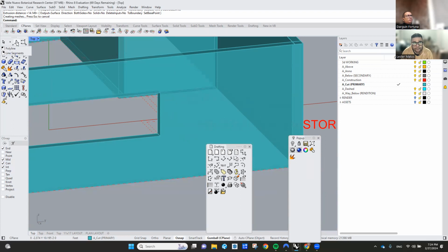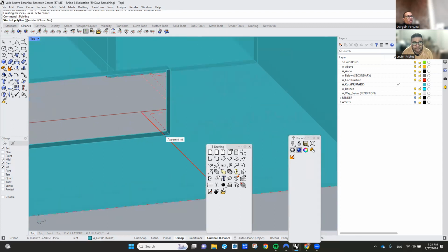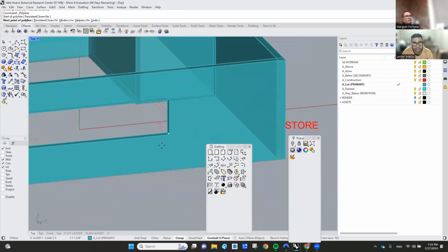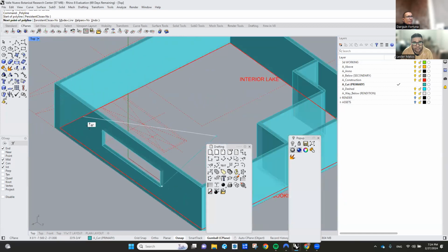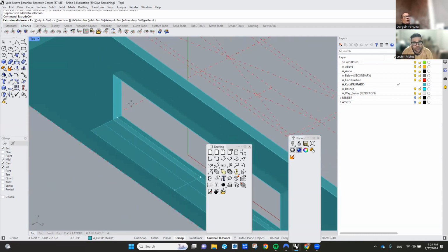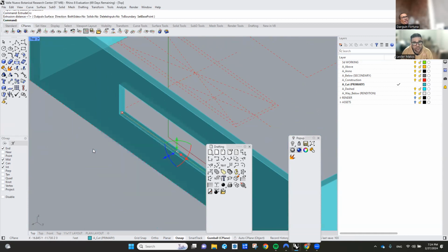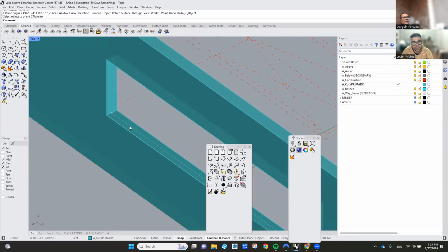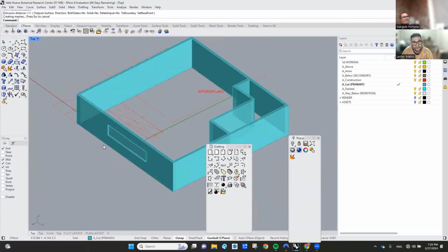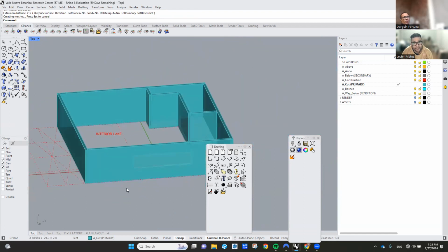Another thing I would want to do, you could grab and use the middle point right here, and the middle point right here. Enter. Say extrude. If you wanted to do like a little glass, now it's using that face to grow, so you don't want that. What do you do? You pick the plane, top face, CPlane, and pick that. And then now you can say extrude curve, and it's going to want to go up. You have your nice glass. There you go. That's your window right there.